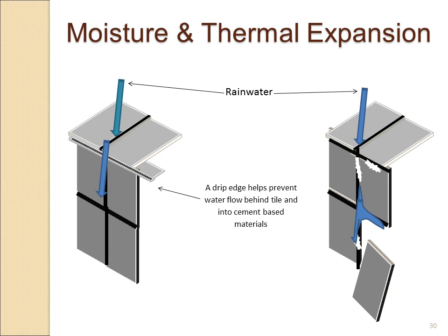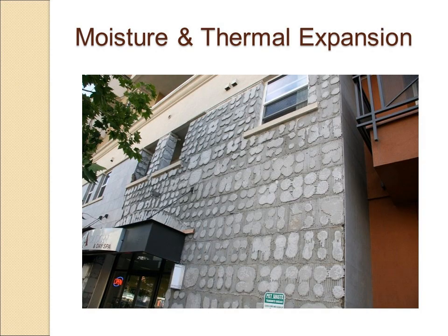So nothing more dangerous than a 12 by 24 or a 2 foot by 2 foot tile falling off 30 feet off of a building. And we're seeing it primarily because the attention to detail with the drip edge was not done correctly. We're also seeing the usual suspects where areas were spot bonded.